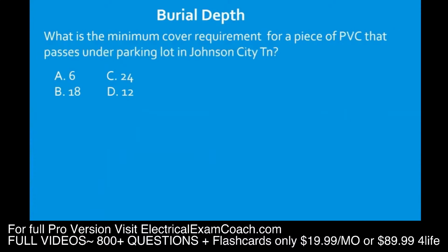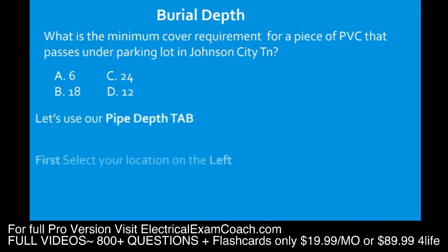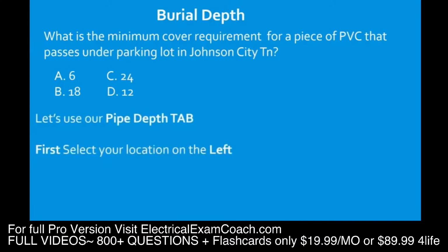What is the minimum cover requirement for a piece of PVC that passes under a parking lot in Johnson City, Tennessee? So the first thing we do is we use our pipe depth tab. We're going to select our location on the left. And if we come here, we're going to find that there is a under streets, highways, roads, driveways, and parking lots.